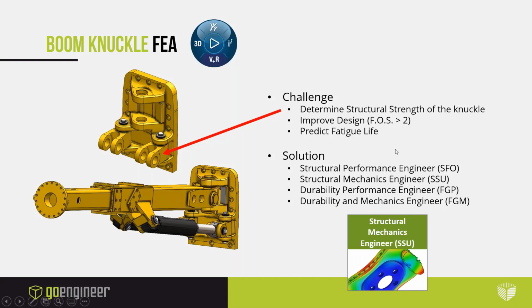Now, as far as the solution goes, we have multiple solutions for structural analysis on the 3DEXPERIENCE platform, but just know that the commonality these all share is they're all based on the Abaqus solver. Each of these solutions gives you an additional level of capability as you step through them. For instance, the structural performance engineer gives you access to the standard implicit solver, while the mechanics engineer gives you access to both the explicit and the implicit solver. So all of these refer to the same technology, but just at different levels.